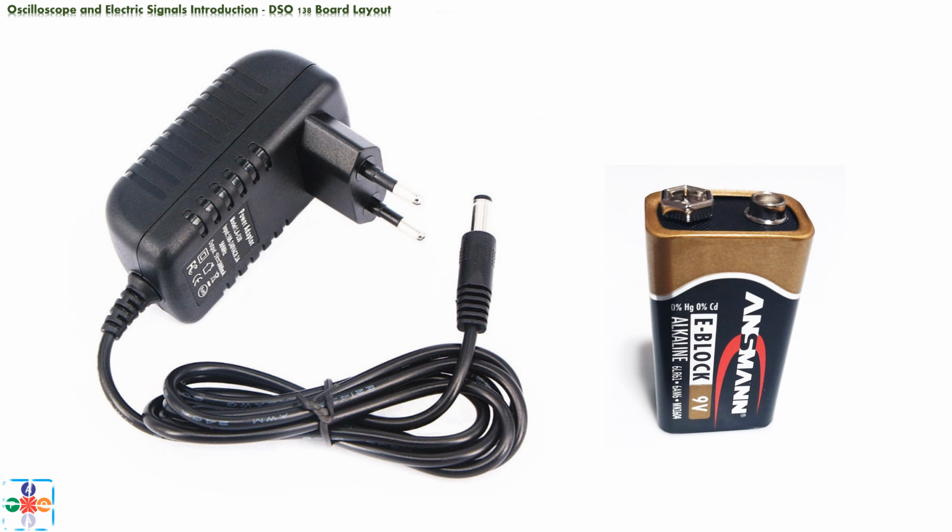Next, you will need a power source to power the device. Now, there are two ways to power the oscilloscope. You can purchase a 9-volt AC/DC adapter, with a barrel connector, and use it to power the device. The other way is to use an independent power source, such as a battery, and power the device using the white connector on the board itself. Make sure that whatever source of power you choose, you match the polarity of the power source and connectors. Also do not under or overpower the device by using a higher or lower voltage power source.